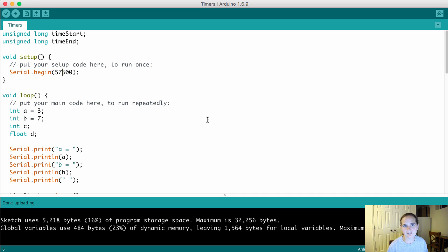So for embedded systems, and in particular control systems, this timing can be crucial. I need to make sure something happens, for example, in an autonomous vehicle at a particular time. And for that we use something that's a lot fancier than an Arduino, but the same principle holds. I still have this central clock. I still have these timers that allow me to measure how long it takes and make sure that something happens when I want it to happen.